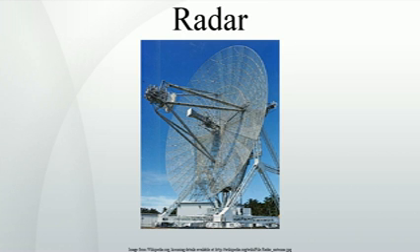In this way, the transmitted pulse of RF radiation is kept to a defined and usually very short duration. Hybrid mixers, fed by a waveform generator and an exciter for a complex but coherent waveform. This waveform can be generated by low-power low-voltage input signals. In this case the radar transmitter must be a power amplifier, for example, a klystron tube or a solid-state transmitter. In this way, the transmitted pulse is intrapulse modulated and the radar receiver must use pulse compression techniques.